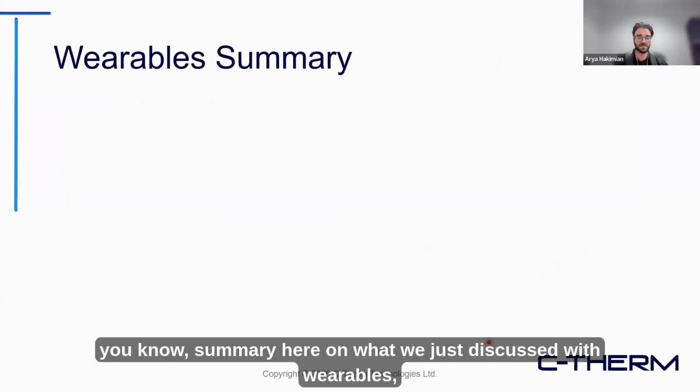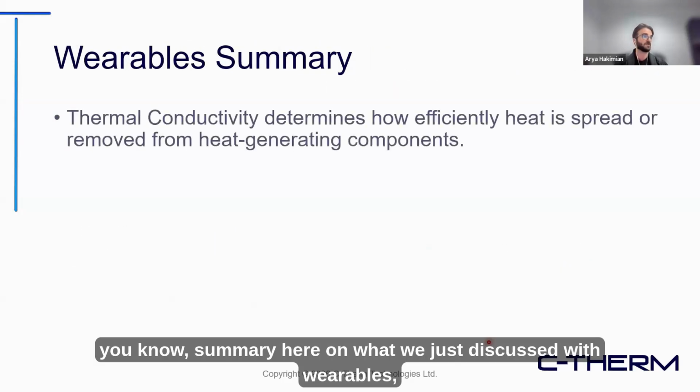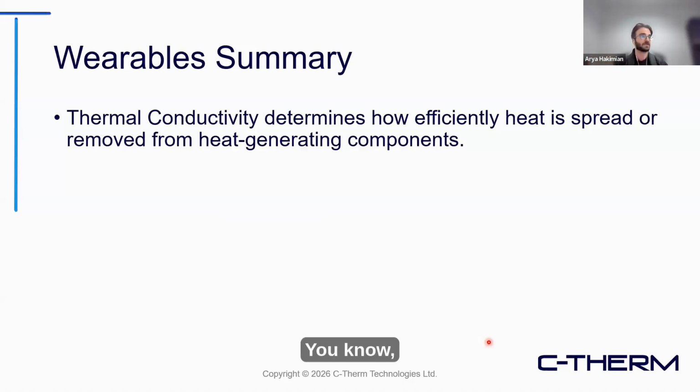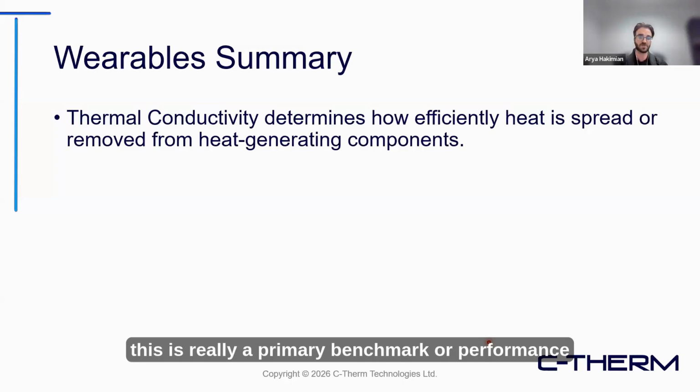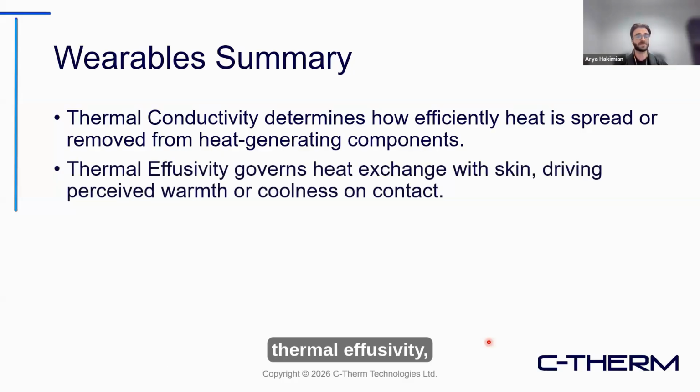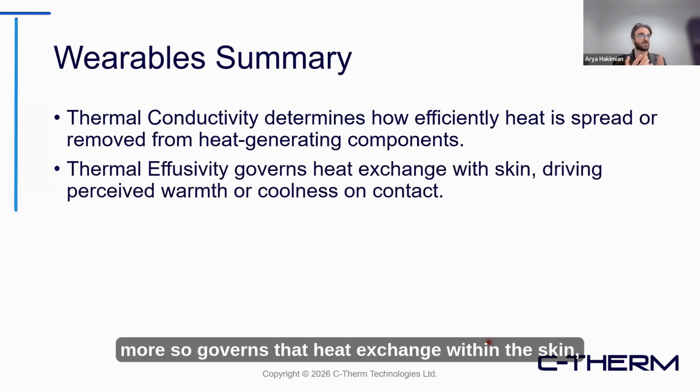So as a quick summary here on what we just discussed with wearables, thermal conductivity is really going to be your core value output when we're talking about how efficiently heat is spread or removed from a generating component. This is a primary benchmark of performance that a lot of folks are, of course, interested in. Thermal effusivity more so governs that heat exchange within the skin, driving that perceived feel of warmth or coolness.